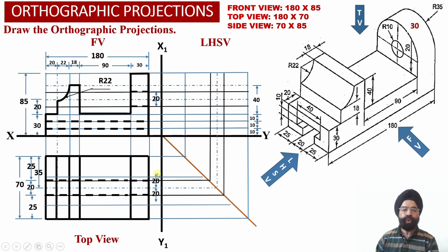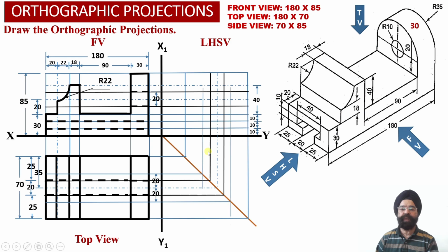So now two horizontal projector lines we have been able to obtain into the top view projections, which are separated by a distance equal to 40 millimeter. This distance corresponds to these two vertical walls of the T slot, this vertical wall and this vertical wall. And these two horizontal projector lines, we have transferred them into the left hand side view projections using this transfer line over here.